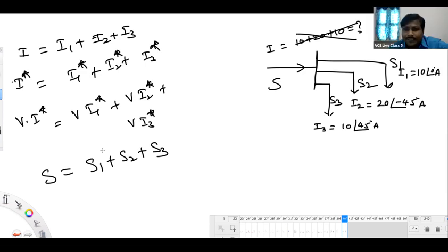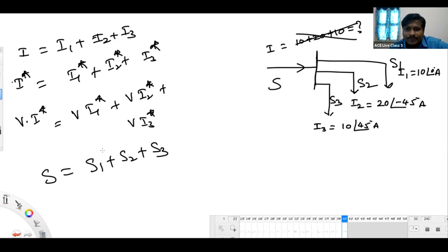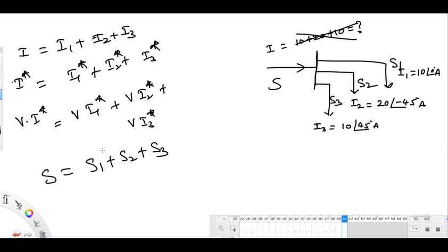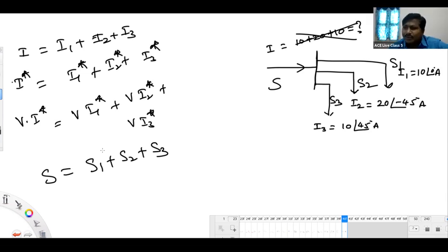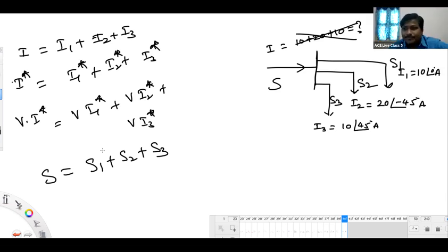Can you repeat again? What is the method we use to absorb the surge, sir? Because of switching over voltage surge. Sir, lightning over voltage is also the same, sir. Lightning arrestor. Sir, is there any difference between them? Difference in the sense, equipment wise, you don't have any difference, but the rating may be different.